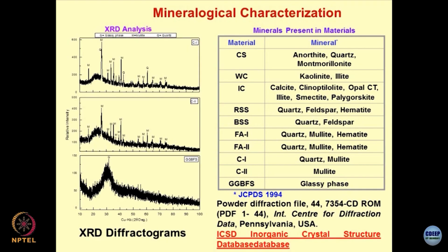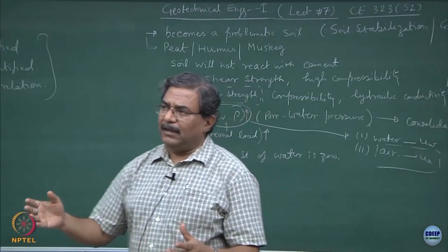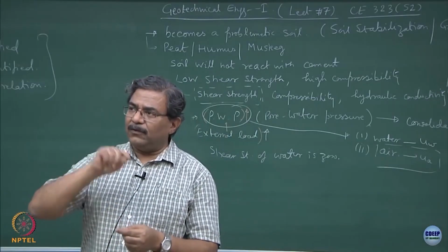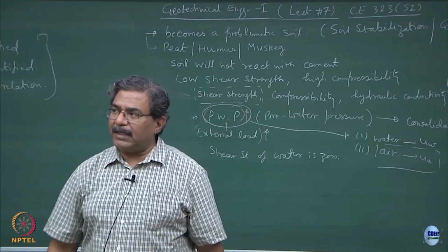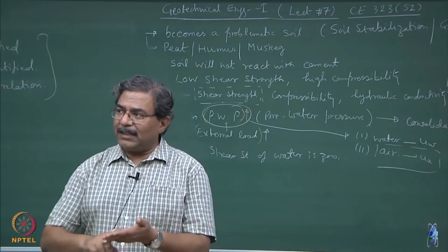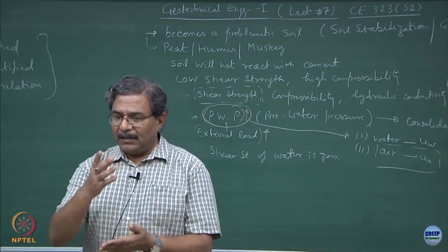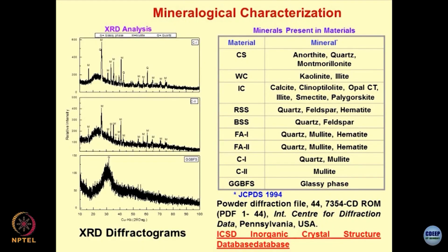But suppose I change my profession and I am doing, let us say, medicine or pharmaceuticals, I do not want crystalline things, these are going to scratch my intestine from inside, is it not? I can't use it in detergents, I can't use it in washing soaps. So, what do I have to do? I have to use an amorphous phase of the material which is soft, gentle, with very high cation exchange capacity and very high surface area, clear. So, this is the difference, depending upon your profession you can select the right one.